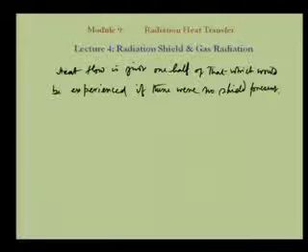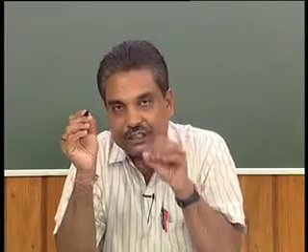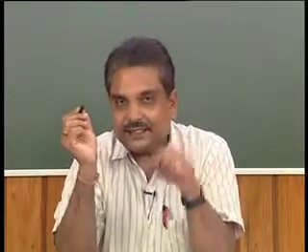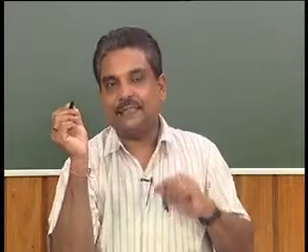So, we just wanted to see that when there is a single shield between two plates, the heat transfer rate becomes half. It is reduced to half of what the original case would have been. But this derivation had a lot of assumptions: all the emissivities are the same, these are two large plates, and their view factors are 1.